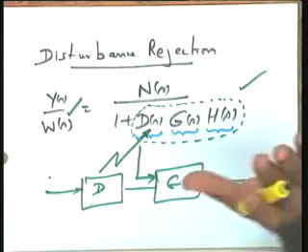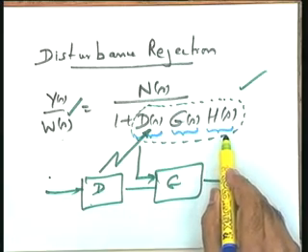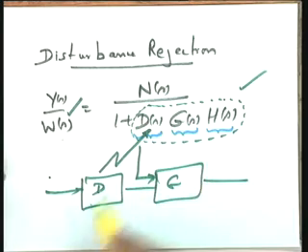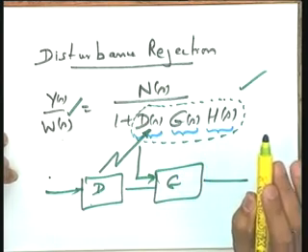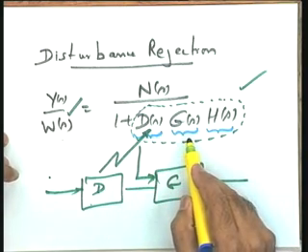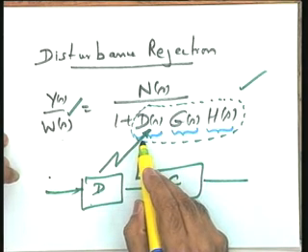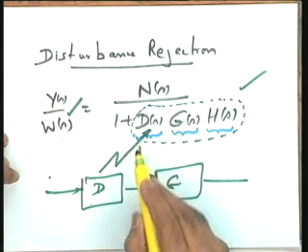The parameters of the sensors cannot be allowed to vary because the system is highly sensitive to sensor parameters. So the sensor is fixed and is given by the considerations of robustness. The design is fixed for the sensor. How about G(s)? The plant gain also, in all probability, in most of the cases, cannot be varied. The plant is a fixed plant. The only parameter which is subject to change, which is subject to design, is the controller.